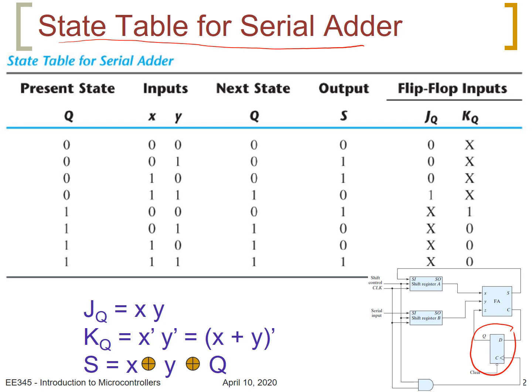The state table will contain one flip-flop which has a present state Q and next state Q, and this flip-flop will hold the carry as we have done earlier. So this is connected with the carry output of the full adder in the previous method.